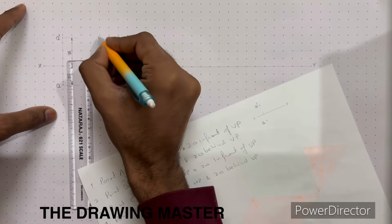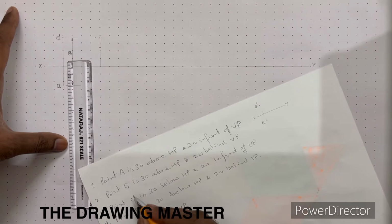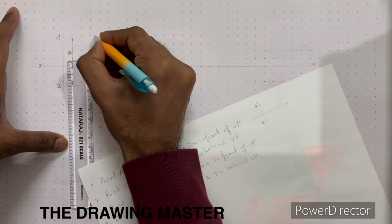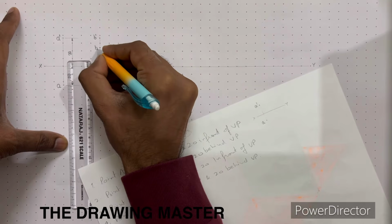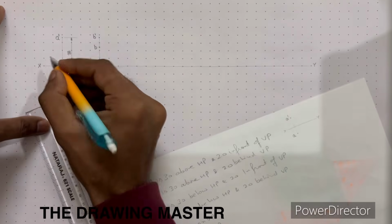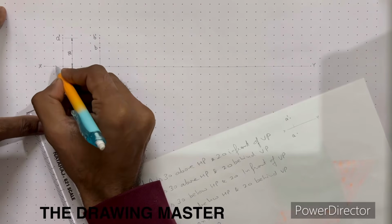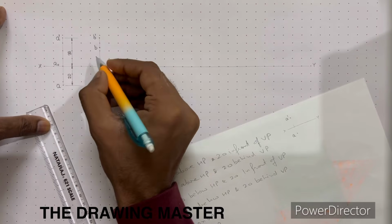So above means above the reference line. This will be the front view. Name of the point is B, so this will be B dash. And this is B. Right? So one more thing you can do: on the reference line, you can write the original name of the point, A naught. Here B naught.